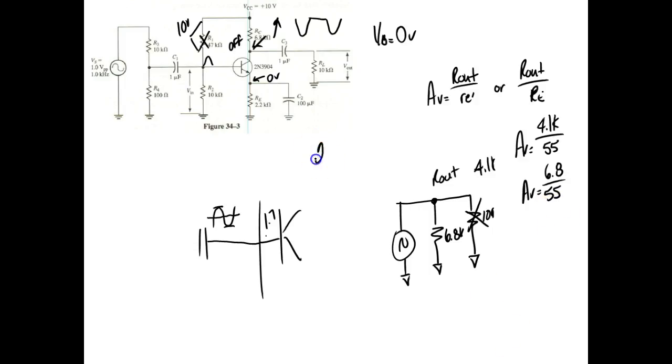So I've got 2.2 volts out. I'm bringing in what? 20 millivolts in. What are you saying, Courtney? It's got to be bigger than 77, right? So what we got? Yeah. So now we're getting a gain of 110. So we're getting 30 over what we thought we were going to get. 110 would be equal to log times 20. It's going to equal 41 dB.